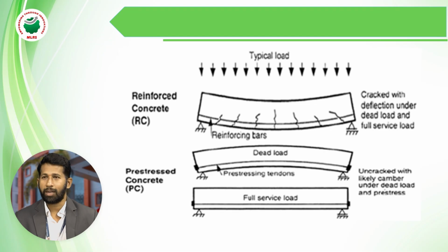So now go through the typical diagram comparing RCC and prestressed concrete structures. Generally, in reinforced concrete structures, cracks will develop, because concrete is strong in compression and weak in tension. That is the reason cracks develop in the RCC member. So now they rectify these cracks. Now Freyssinet introduced the prestressed concrete structure in 1904. In India, the prestressed concrete structure was in 1948 in Rameswaram, Tamil Nadu, the Pamban Road Bridge.